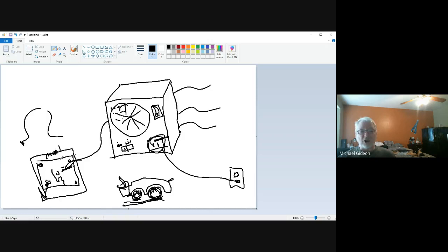So if you happen to be out on site working on someone's computer and they don't have a grounding strap or an anti-static mat or something like that, you can set the computer on the table, touch the case, anything bare metal, and you've just become the same potential as that computer, and you shouldn't fry anything with static electricity, okay? Just keep that in mind.